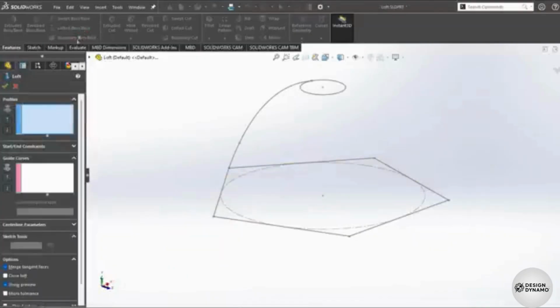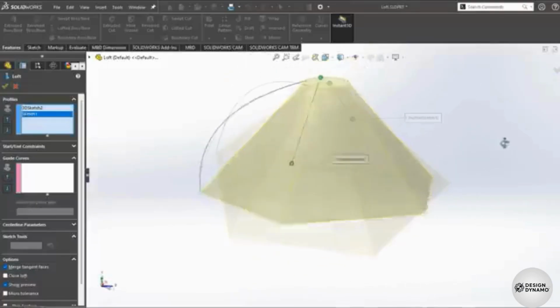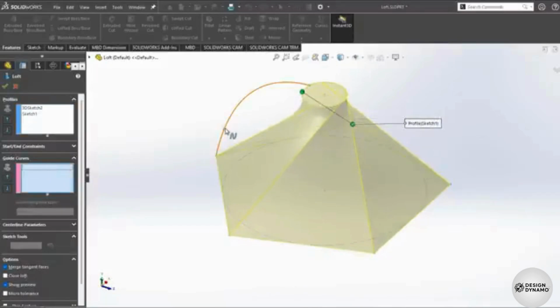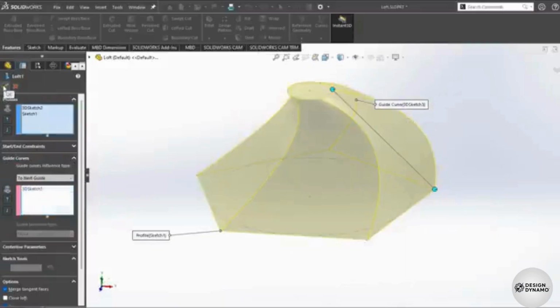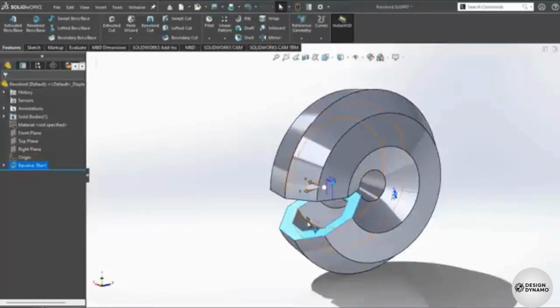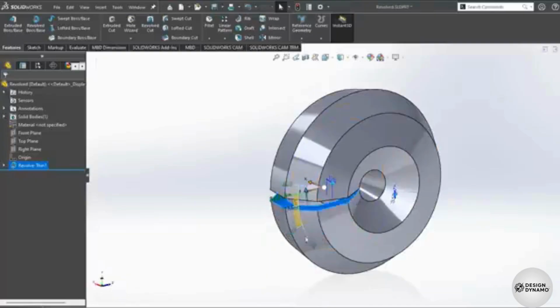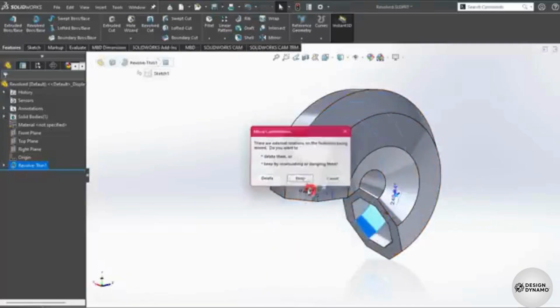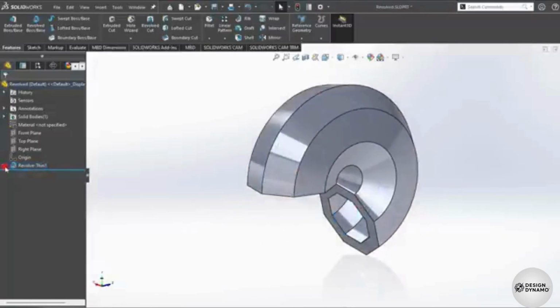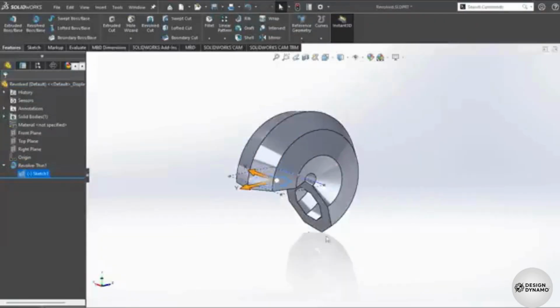Enable Loft to select the blue profiles to use as a section, applying at each step, and connecting these in the correct order. There is also the possibility to specify a guide curve in pink color. To edit these 3D features, you can select any face or contour and use the arrows to adjust the extrusion or move these. You can also modify the subcomponents to reshape the entire object.